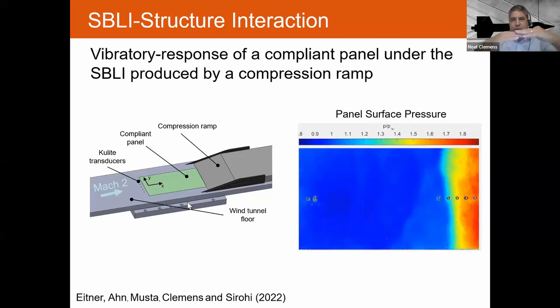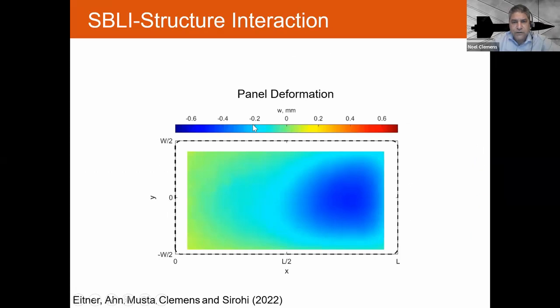So we can sort of match the pressure above and below the cavity when the tunnel runs subatmospheric. Anyway, so that thing moves, and we basically use DIC. We paint the bottom surface with a bunch of dots, and then we image it with 2 cameras, and we get the out-of-plane displacement of the panel, and that's what I showed here.